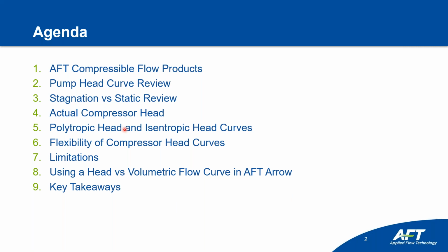To start, I'll do just a brief overview of our compressible flow products. And then as review to kind of build up to the compressor head curves, I'll talk about pump head curves and their nuances and static versus stagnation properties, some of the nuances of that. Then I'll get into what an actual compressor head curve looks like and how compressor head kind of comes from thermodynamics and it's very different than pump head curves.